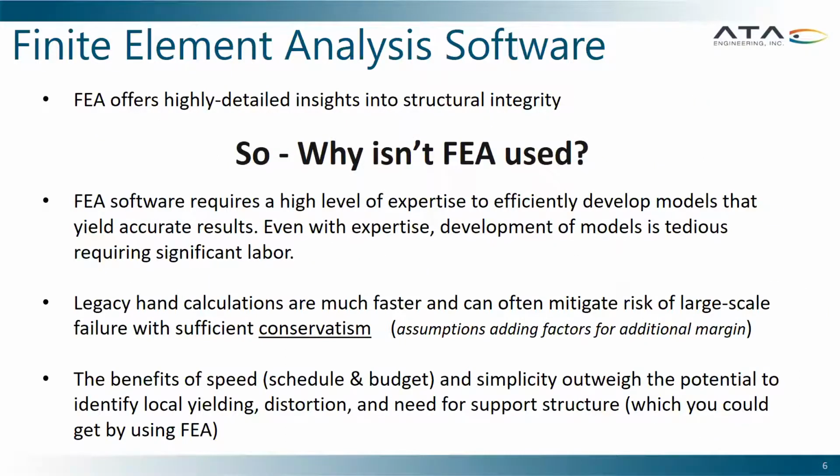FEA, as I'm sure all of you know if you've been using Femap, offers highly detailed insights into structural integrity. Simulating something like a lift in Femap is going to tell you about local yielding, any distortion or buckling that's going on, and the need for support structure to be added before you do the lift. So if FEA is so great, why isn't it being used more?